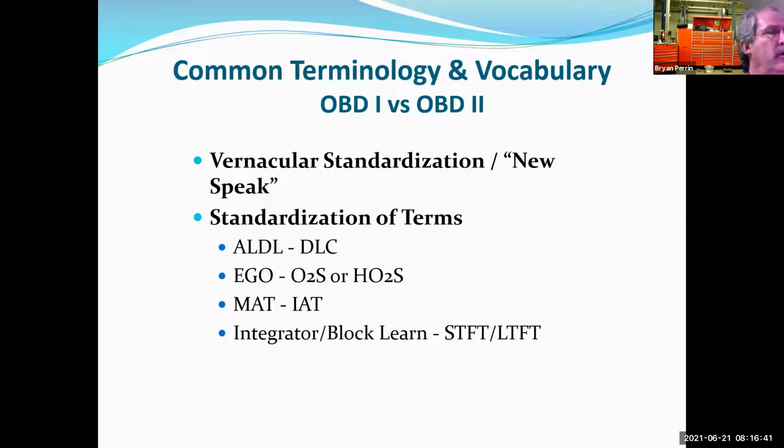Integrator and block learn are now short-term and long-term fuel trim. So those are our manipulated values for fuel trim. So we also had other things like adaptive and multiplicative. I mean, we had all kinds of different names to describe that short-term and long-term strategy. OBD2 said, no, this is what you have to use. This is what you have to show the technician on an OBD2 scan tool. You have to give it to them in the same scale, same terms, regardless of which vehicle. So you can see why,